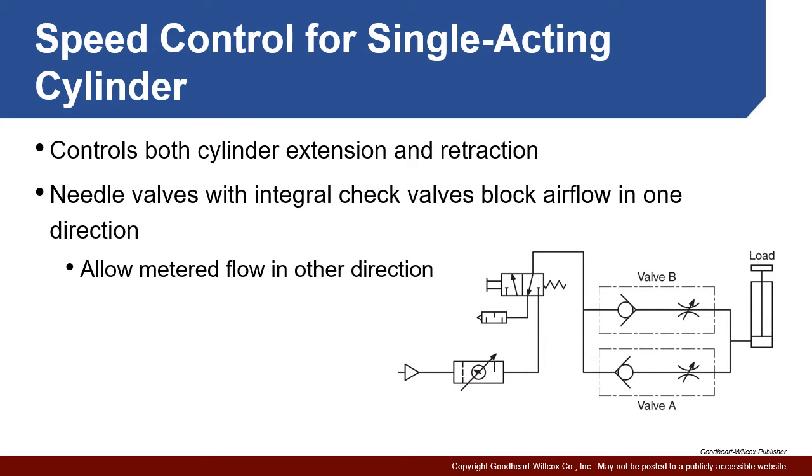The simplest example of this is a single acting cylinder that we want to be able to control the speed of extension and retraction. So here we have our system. Airflow coming in, our FRL unit comes to a three-way directional control valve. Here's an exhaust with a muffler on it. In a normal position, it would actually be draining the air out. Once you push this button, air goes through. Obviously, this check valve is going to stop the air from coming this way. It comes down here, and it pops this open, flows in, and extends it.